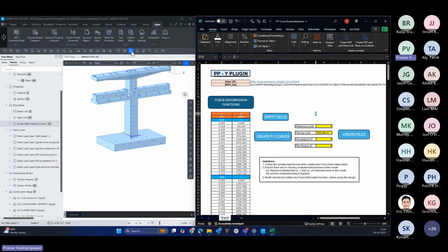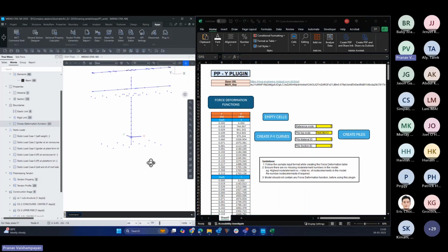I'll just turn off this view so we can quickly identify. Let's say we are going to choose a datum. If we select this, okay, some other nodes got selected. We can see node 7. So you can enter node 7. It is already pre-entered, but for your own satisfaction and to understand how it will work for different nodes, we can enter 7.